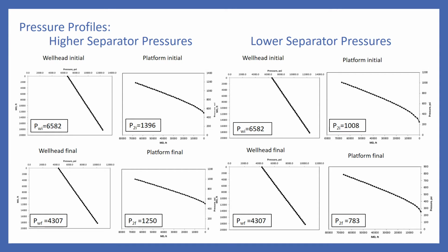Although this did raise our P2 over 200 psi for the initial case, the wellhead pressure is well beyond twice the P2 needed for critical flow. P2, however, did stay higher for the final case than the base case and for most cases we observed. This could pose problems for wells that do have wellhead pressures that would cause the flow to reach subcritical levels.